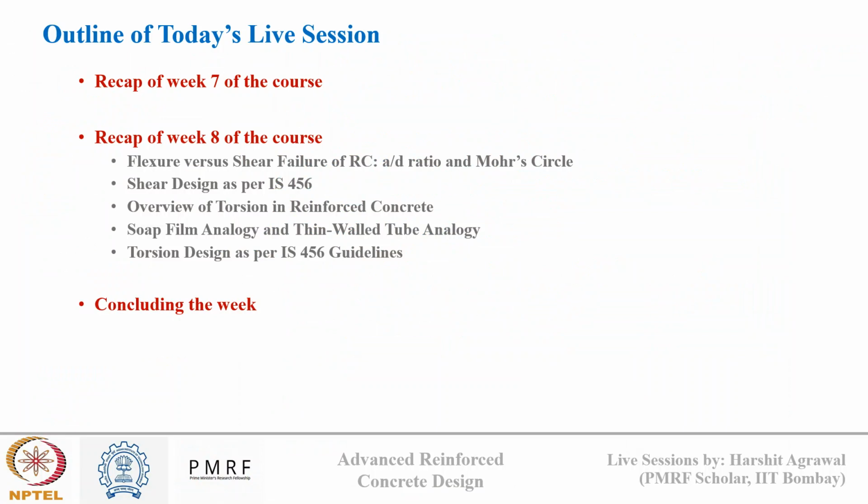After shear, we'll start discussing torsion in reinforced concrete. What is torsion, how torsion cracking occurs, what is the science behind torsion, and how we estimate the maximum torsion stress based on soap film analogy and thin walled tube analogy. And finally, we'll see how torsional moment is incorporated in RC design as per IS 456.